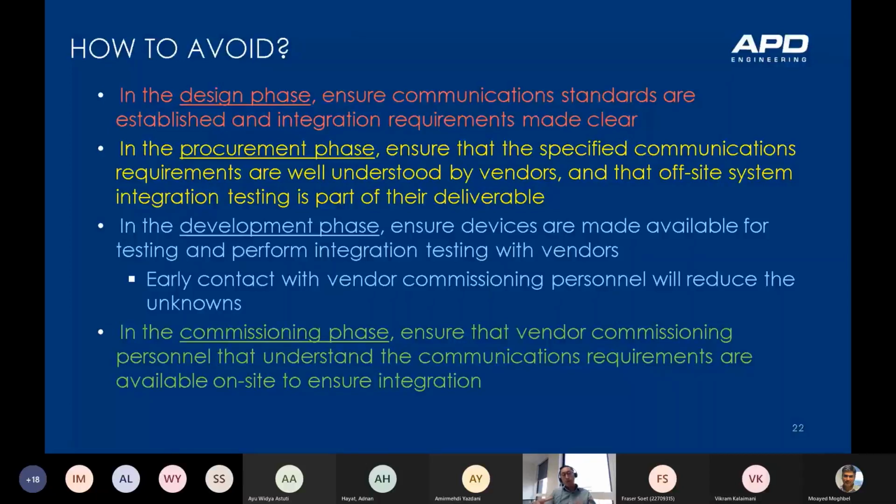Also reduce the unknowns. Hopefully they've got specific skilled personnel who can actually help you on site. And of course, in the commissioning phase, ensure that the vendor commissioning personnel that understand the communications requirements are also available on site to ensure integration, and you're not trying to do this over the phone to someone that is difficult to understand.